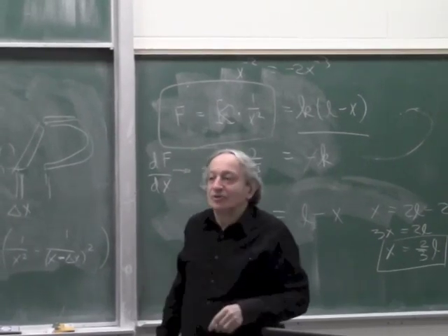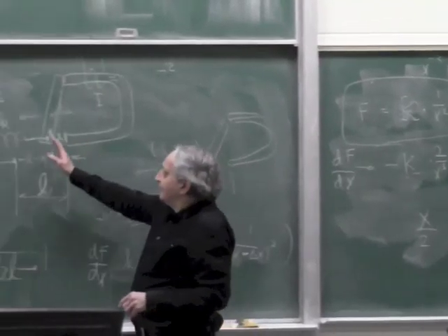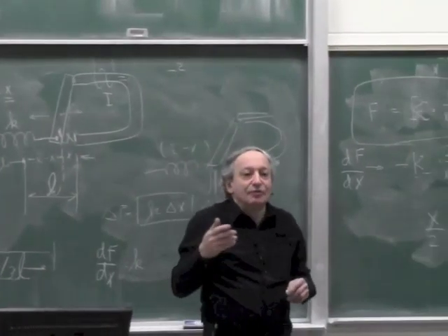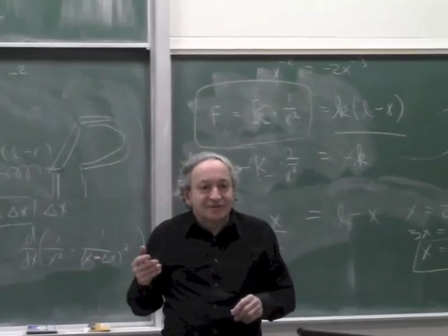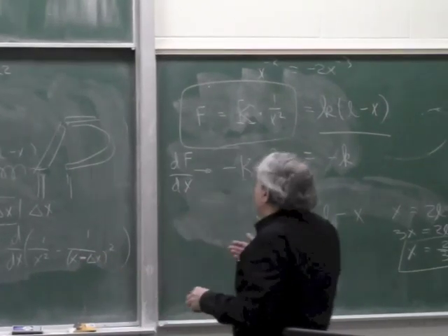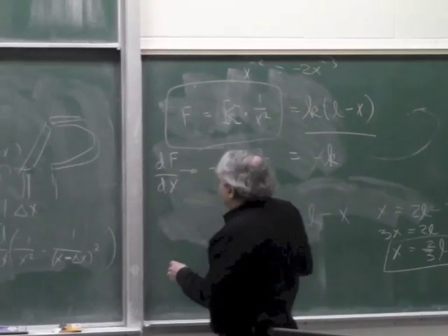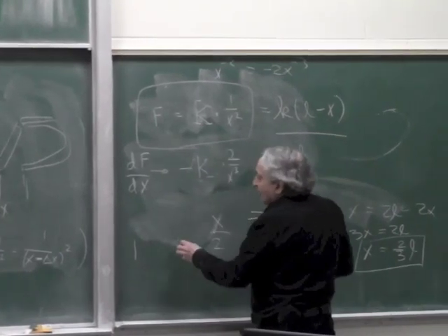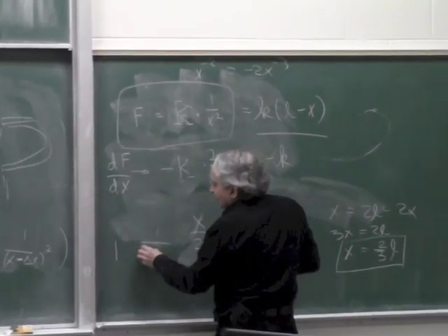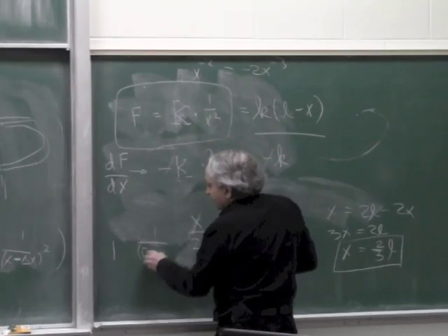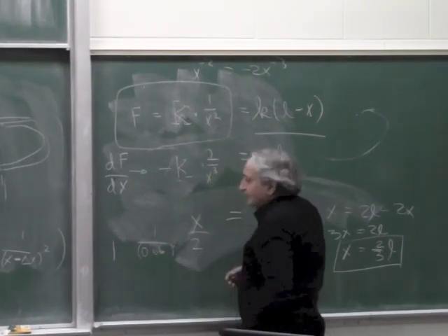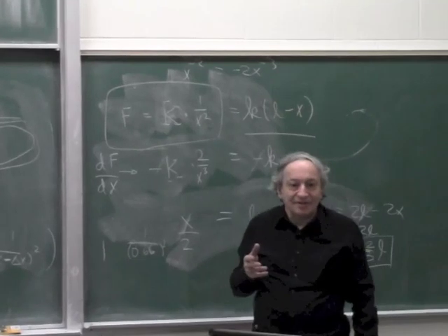And then they're also not good, because even on this 1/3, the gain of the servo will change. Okay? And we can calculate by how much it will change. It will change by the ratio of 1 compared to 1 over, say, 0.66 squared. Okay, so it changed by about 50%.